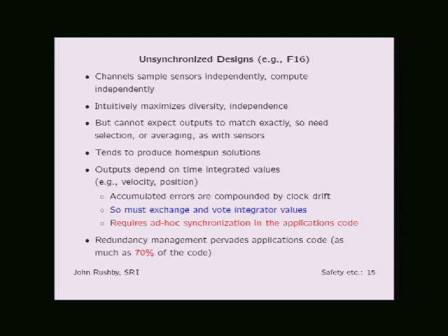From this velocity reading. Now, of course, what can happen is if these are sampling slightly different values, and if it just happens over a short period of time, and these values are not too different, then if these time instants are close enough, you would expect that even though you're integrating over these values, if you're doing it for a small time interval, then the drift is bounded, right? But if you do it for a large time interval, then the drift can get quite significant. And in that case, these two computers would disagree significantly on the position of the plane, right? So if outputs depend on values that are time integrated, then if you have unsynchronized designs, there can be a large drift in the outputs over a significant period of time, okay?